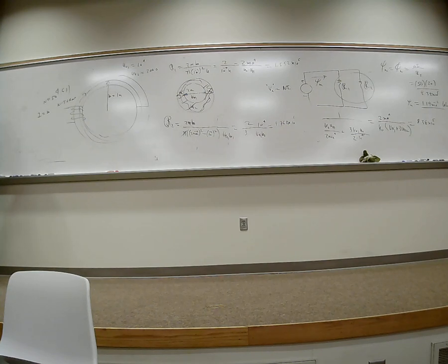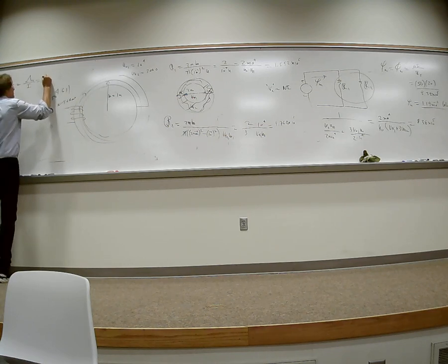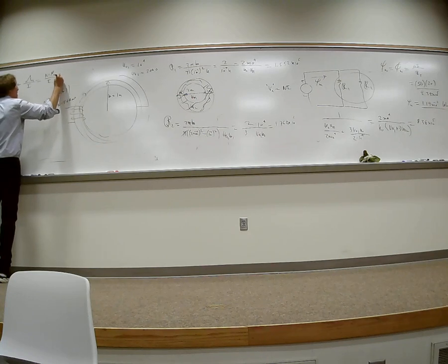So the next thing I'm going to do is get the inductance. This is going to be the self-inductance. Now, inductance is always the total flux, which is really going to be, the symbol they use in the book is this, divided by the current causing it. Well, that symbol right there is called flux linkage, I think, in power and stuff like this. It's just the number of turns times the flux per turn over the current causing it.